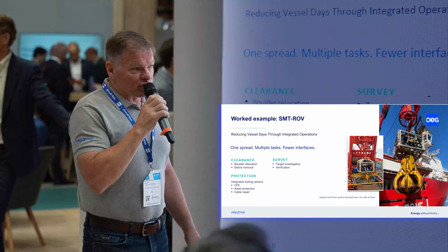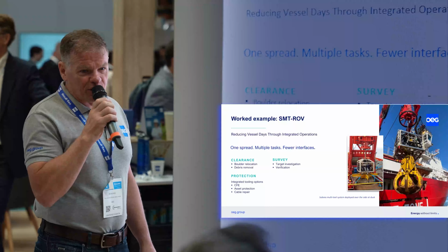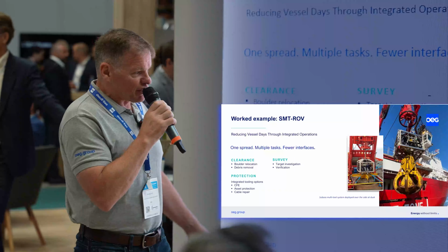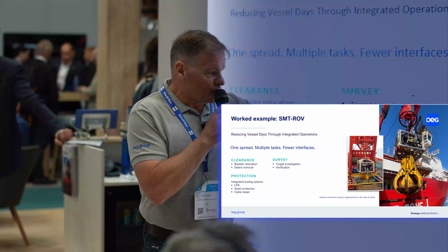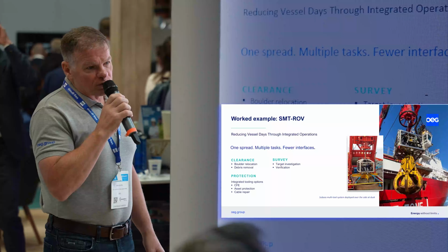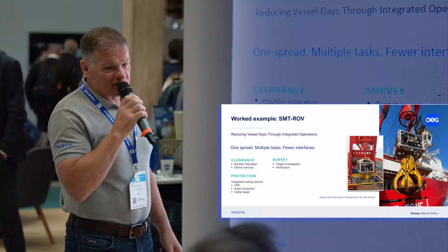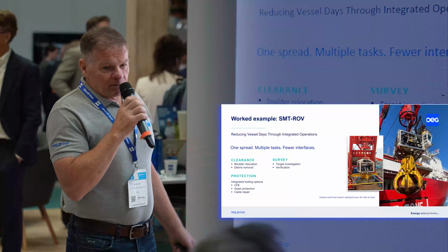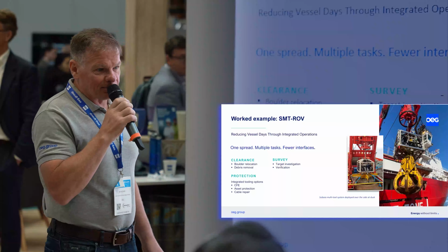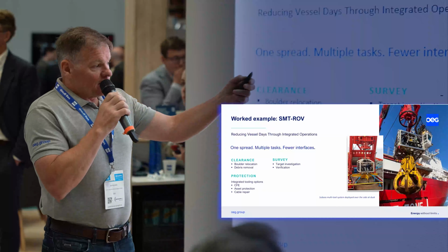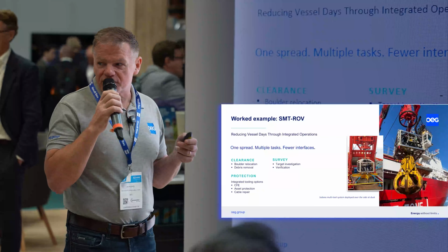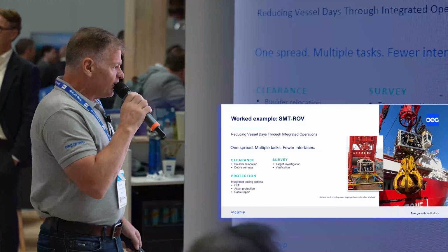Our own subsea multi-tool, it's the Swiss Army knife of a ROV, is another way of putting it. It's a bolt-on system, and as you can see there, you've got the tine grab, and we've got a rock bag installation cruciform. So on one site, we can do multiple tasks with this. Everything from removing the pebbles, and we have a clamshell grab, which is a big bucket type grab system, the tine grab, and a mattress installation tool, so we can go along on one project with one vessel. We can do multiple tasks as part of that when we're going forward.